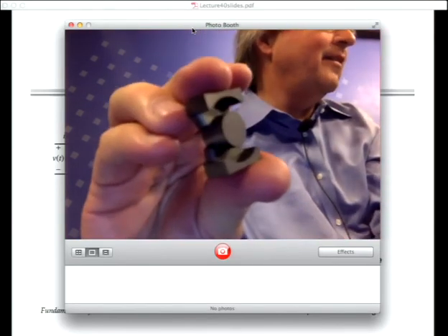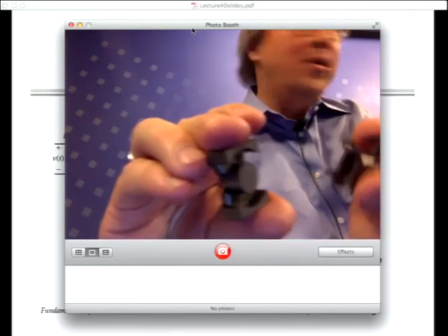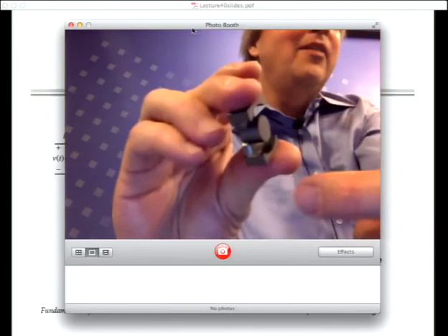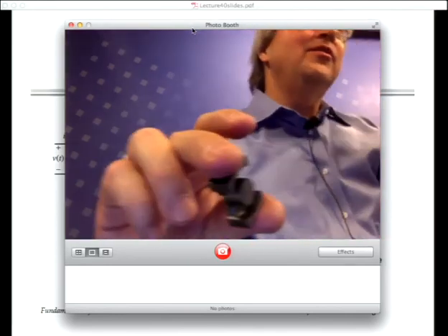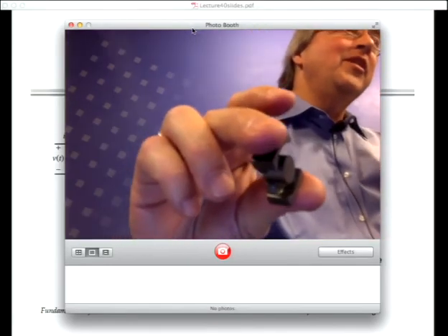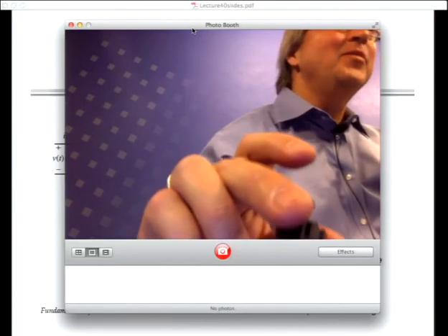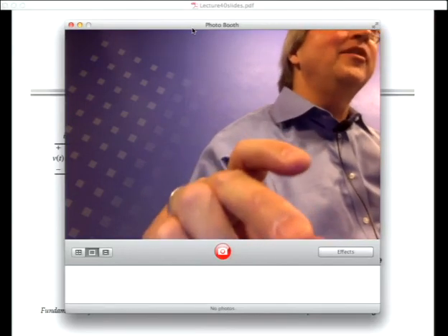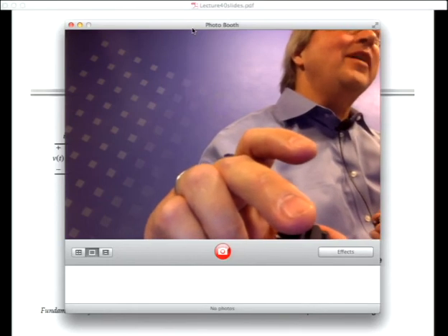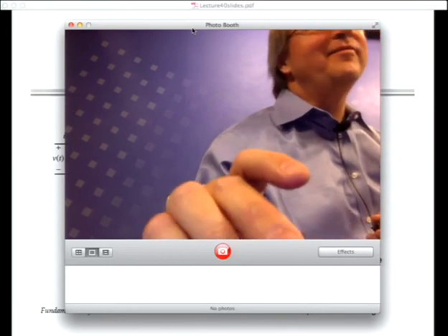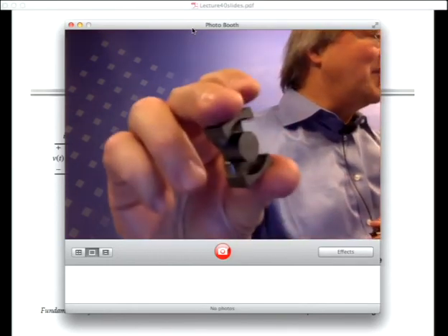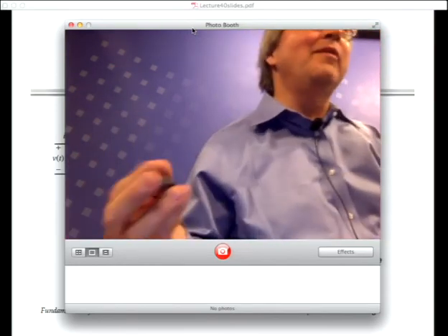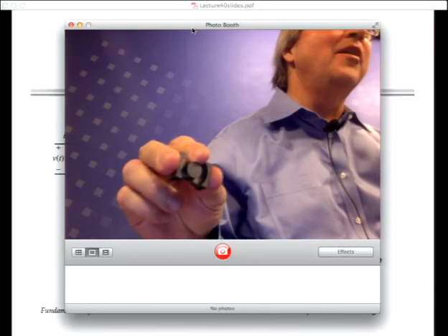You can see that. So when you put the wire on the bobbin, which is round, the wire goes around this round center post, and so one turn has the minimum length, which minimizes the resistance of the wire. Some cores have square center posts, which are easier to make in ferrite, but they're harder to wind. So a round center post is nice. Okay, probably more than I needed to talk about so far.